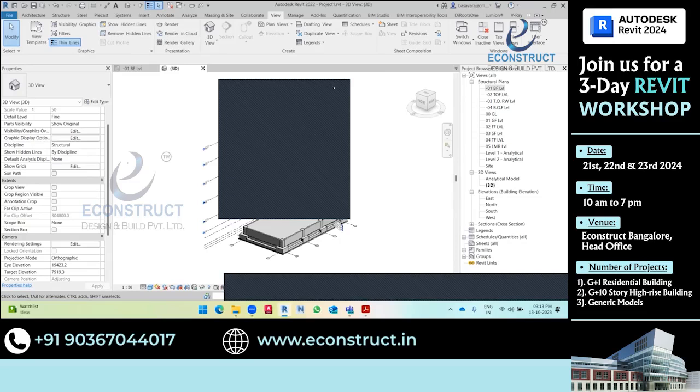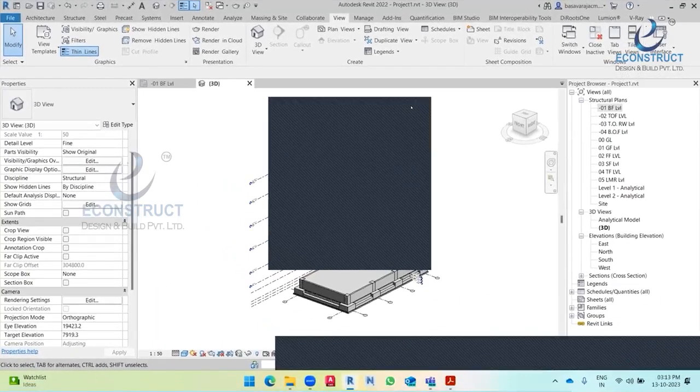Yes, that is fine. But if you're doing architectural drawings, the basic things also need to be visible, like doors and windows and walls. It will. Those are all the default settings. Revit will take them automatically. If you want to change, depending on the need. See, sometimes what will happen, if the door height is 8 foot instead of 7 foot, during that time you need to change the view range top plane.